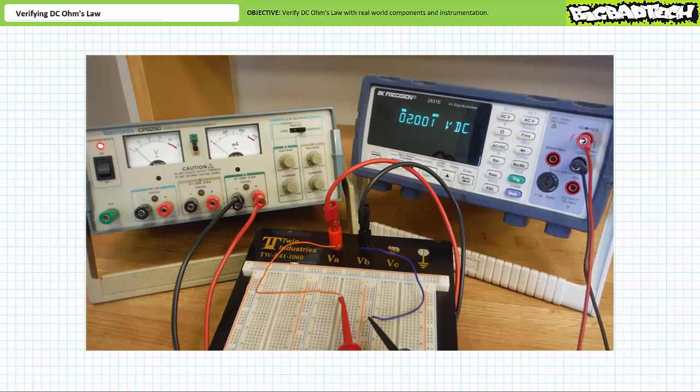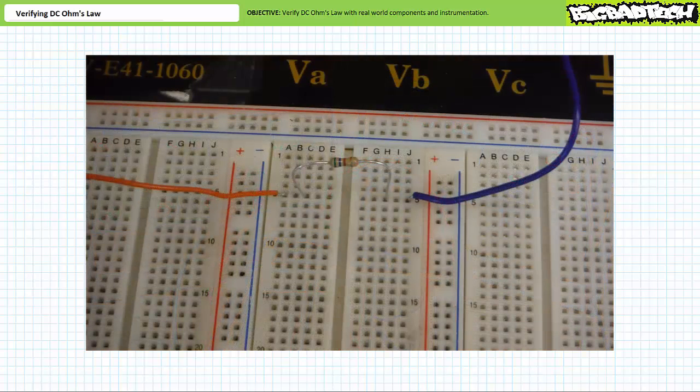First, let's use a DC voltmeter to establish a 2-volt differential. This is the unloaded voltage, meaning it is the voltage established by the supply when it is not providing current to a circuit. We need to build the circuit and recheck voltage in the loaded condition to make sure it hasn't changed. Turn off the power supply. Again, let's current limit this source to 1/4 of 500 milliamperes, or 125 milliamperes, by turning the adjustable current limit knob 1/4 turn clockwise.